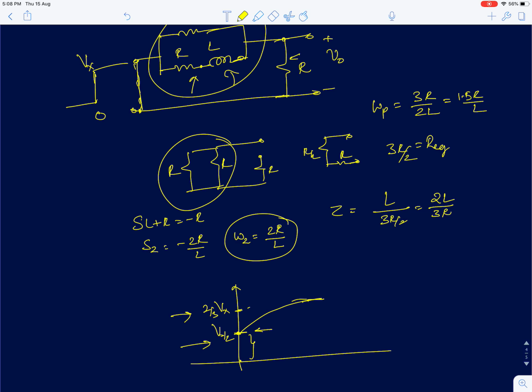You can have more than one inductor, but still the order of the circuit can be just first order if certain conditions are met. We discussed a few examples where such conditions were met. I said if there is a linear relationship between the voltages across inductors, then it can be a first order system. So using those tricks we can very easily guess the outputs of first order RL circuits. So I'll stop at this point.